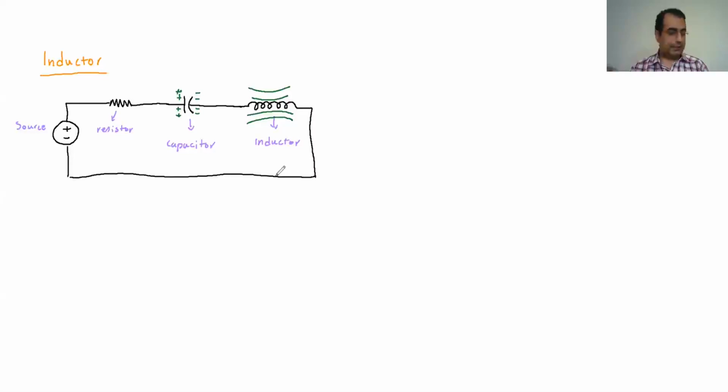So if you're working with a board or circuit that is not connected to the source, it doesn't mean there is no energy in there, because these two elements might have energy, and if you touch it with something conductive, like the hand, there's going to be an electrical shock, and suddenly it's going to release the entire energy. Because it's all released like that, it can be really dangerous.